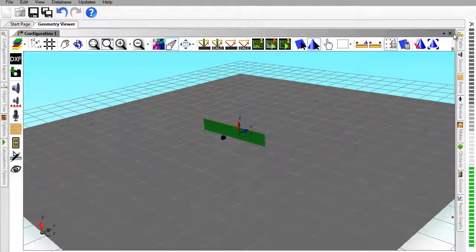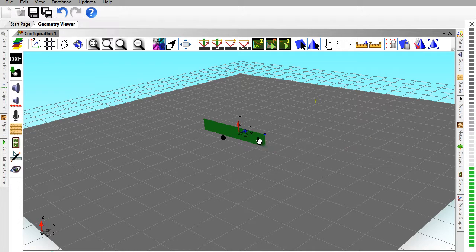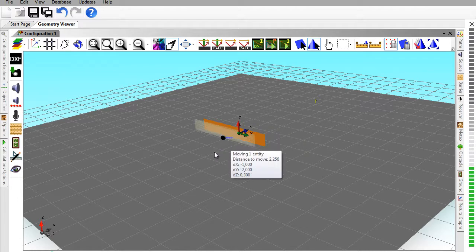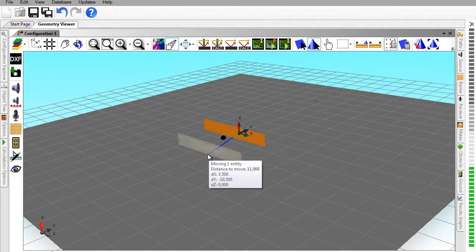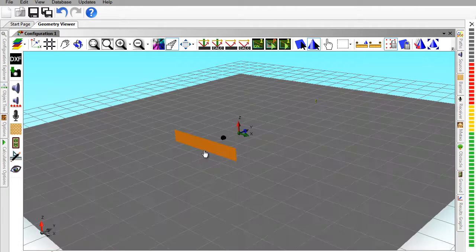You may have noticed this bar on the right hand side of the screen. This is the excess noise level bar. It gives you an indication of the current situation without the need to have the results graph in view. Like in this case, where the barrier has no effect in attenuating the sound, it reaches the red color. Yellow means you are marginally inside the noise criteria, and green that you have solved the noise problem.